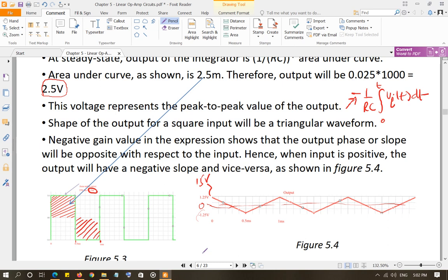This will be 15 volt right here, and then it's going to go from 15 volt, minus 1.25 minus 2.5, which is going to be 13.5 volt, to 15 volt to 13.5 volt to 15 volt, and so on and so forth. And that's a problem with the true integrator. But in any case, ideally, theoretically, it should be about the x-axis, and this should be the output of this circuit.